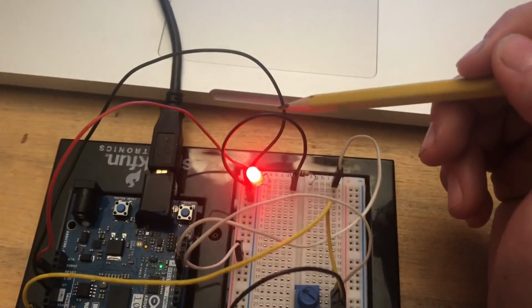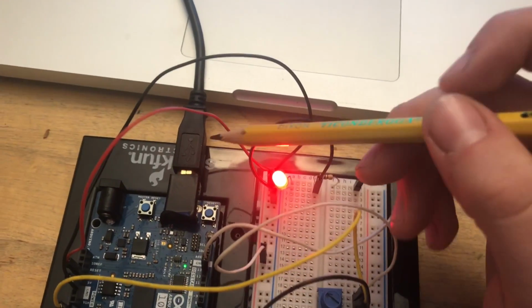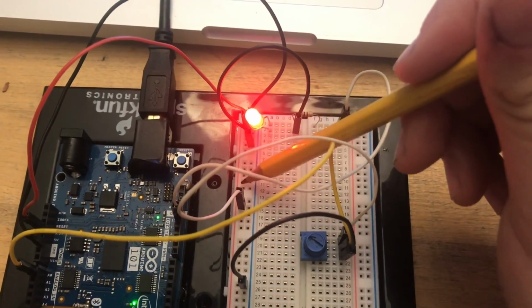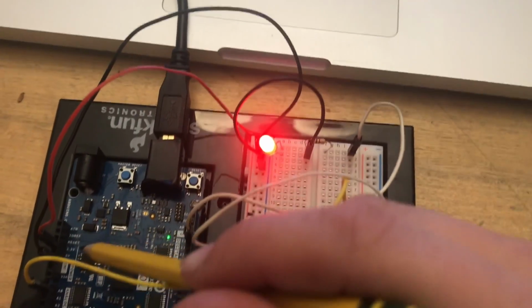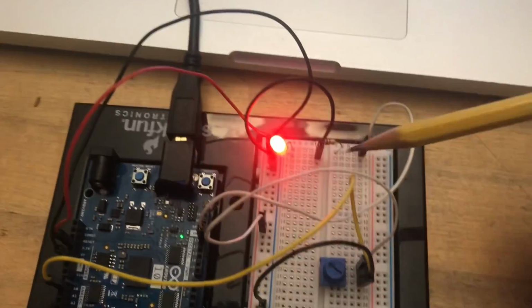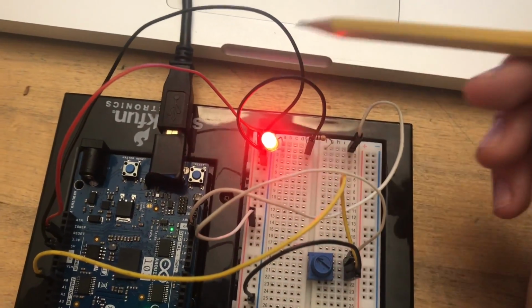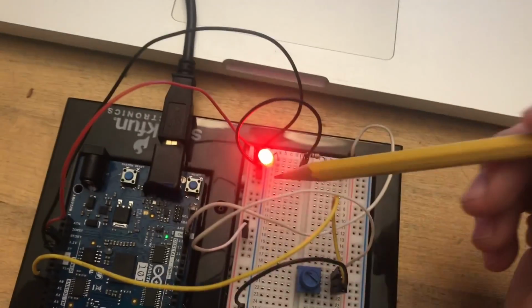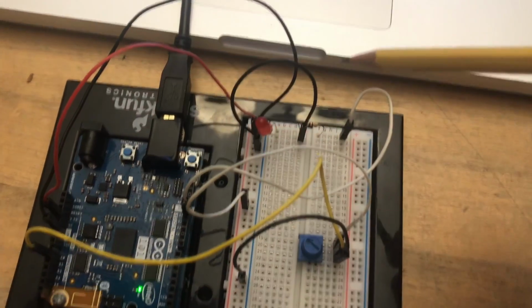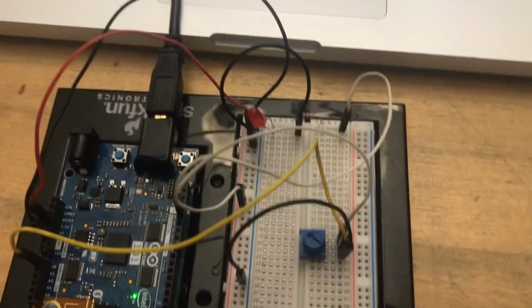And then this red wire here connects these ports from the power strip into the 3.3 volt pin. And this black wire connects these grounds to a ground pin right here, so making this wire grounded for the LED.